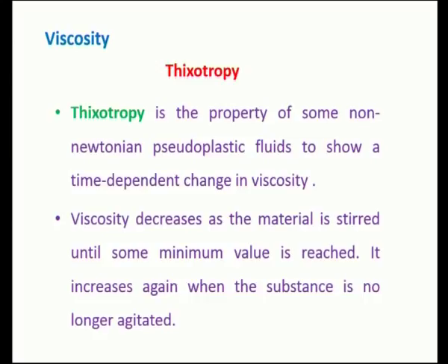And another category is thixotropy. It is again another non-Newtonian type, similar to pseudoplastic fluids, except that there is a time dependent change in viscosity. The viscosity does not depend on shear rate alone, it also depends on the time, how much time the polymeric melt or the liquid is subjected to shear rate.